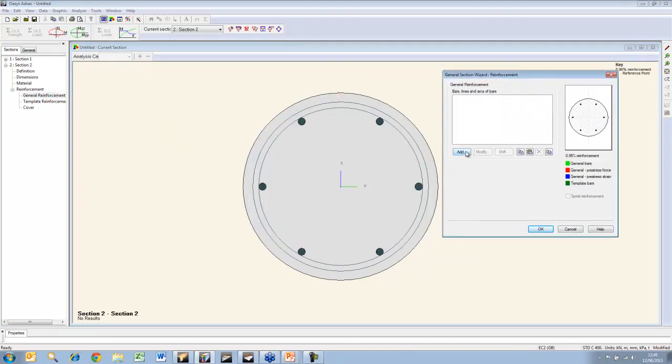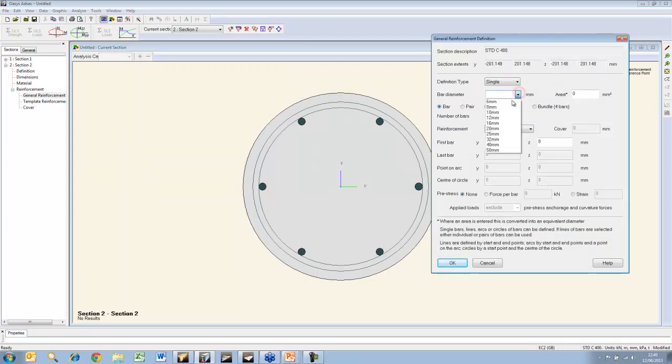We can also add in pre-stress bar, let's say 20mm bar, straight down the middle, and I can pre-stress this under load. I can also then say whether the forces that we're applying for the load cases and everything will include the anchorage effect. So does this preload need to generate additional moments and axial loads on this section, or are they already in there?